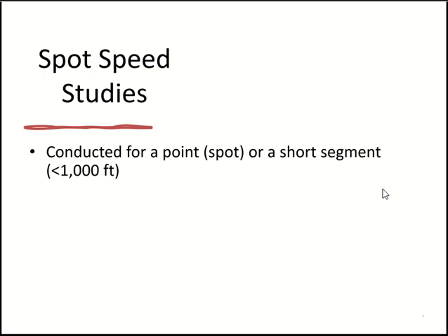If you have a device, you can directly measure the spot speed, no problem. But sometimes we have a restriction that the device is not available. Then what do we do? We do distance upon time. So for that, you need distance.